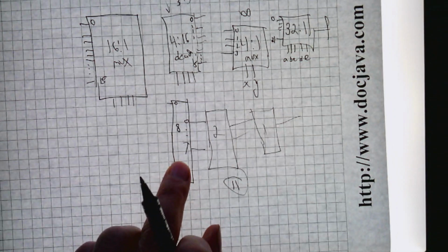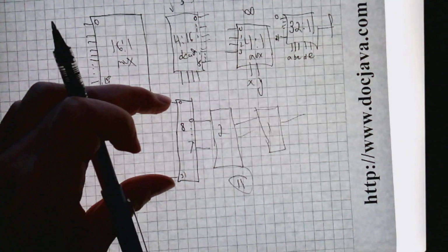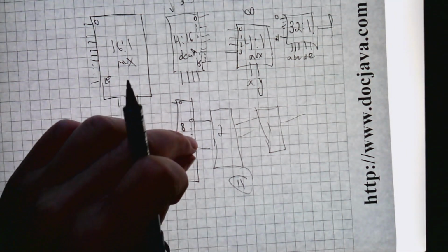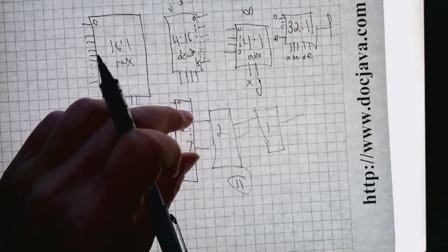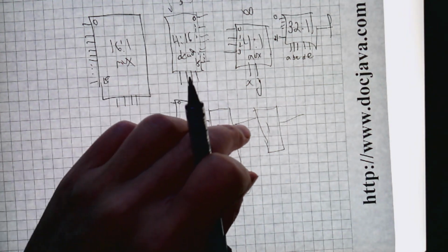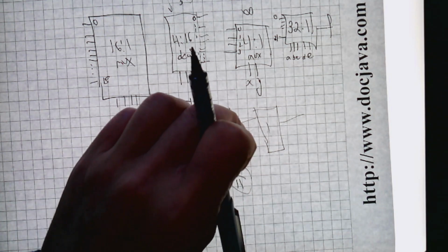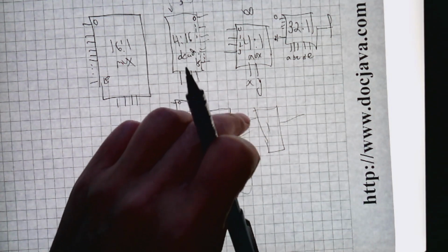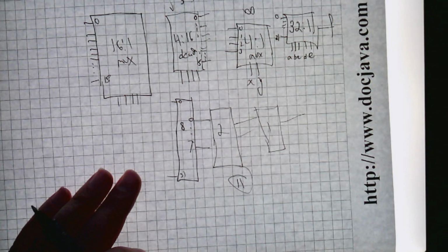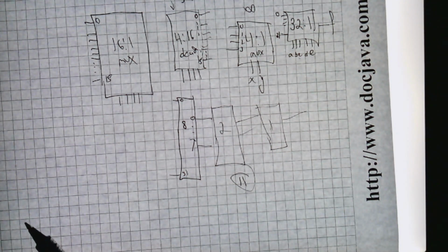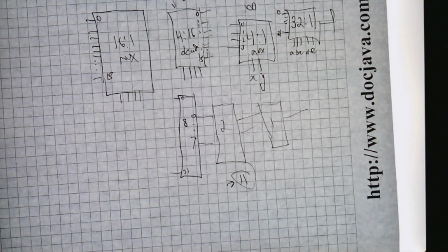Because 8 will give me 8 times 4, or 32 inputs, but it'll give me 8 outputs. And then 2 will give me 8 inputs, only 2 outputs. And then 1 will give me 4 inputs, but only use 2 of the 4 inputs. And I'll get 1 output. So I need 11. Did everybody kind of understand that one? Who got confused? Nobody? All right. Next question, please.